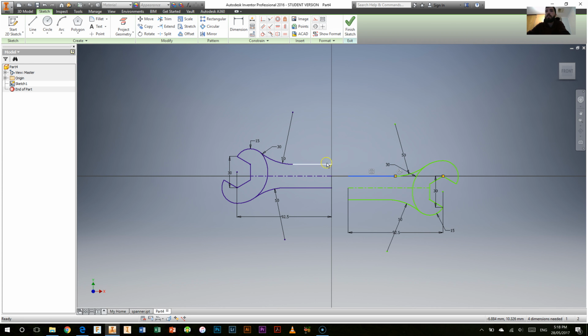So it hasn't linked them up entirely. I'll just hit undo on our keyboard. Actually no, we'll leave it like that. So to start off with, we do need to add in a collinear constraint between these lines and the ones on the opposite side. So I'll do that for each of them. That's going to open constraint, so I won't need to do that one.